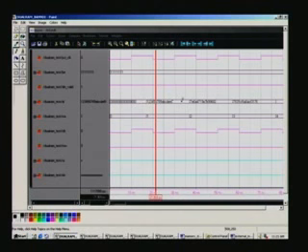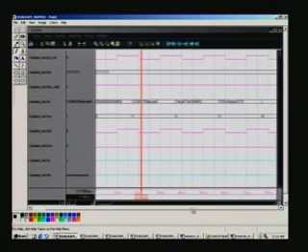So that is the second one. Third was 7E 6A and so on, and like this you just remember. And we have some more here, that is a write address here, it is showing 0 here, 1 2 3 4, that is what I have forced in the test bench, and no read address here because we are writing the first block. There is a system clock here, the dual RAM operates on this clock, especially for the read mode, and we have an R and W control here, it is precisely 0 here, that is what we have done in the test bench.